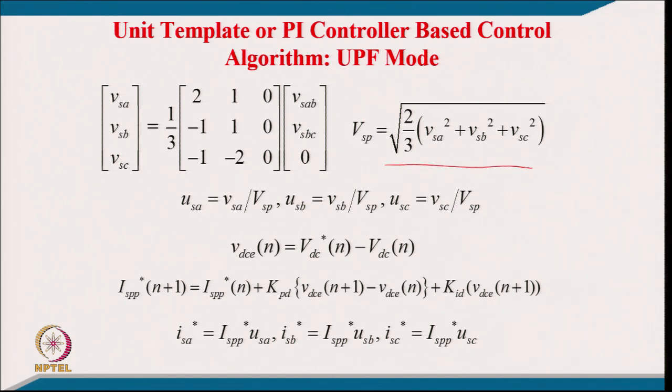These two currents go to either a hysteresis controller, which typically, with the hysteresis band, gives the switching for the inverter devices for all 3 legs based on A phase, B phase, C phase, or we can use any other current controller, like a proportional PI controller, and then the PI controller output of course has to be compared with your carrier wave of switching frequency. So then you will get a fixed switching frequency of your D-STATCOM. Otherwise, in a hysteresis controller the switching frequency may vary.